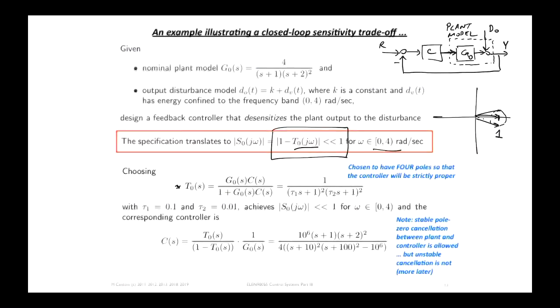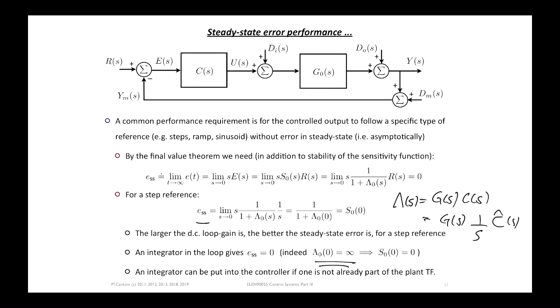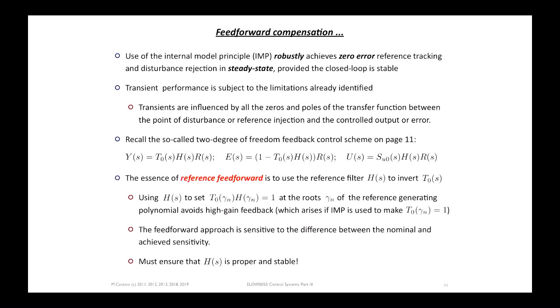So that extra degree of freedom can be exploited in control system design in a way that corresponds to open loop control, where you're effectively inverting the complementary sensitivity function, to improve your reference tracking performance. With this extra degree of freedom in place, the output signal will not just be the complementary sensitivity function times the reference. It'll be the complementary sensitivity function times this